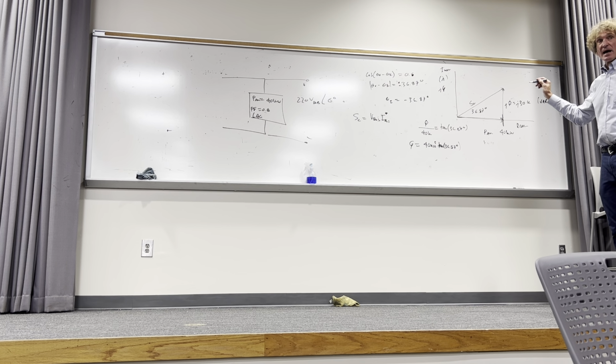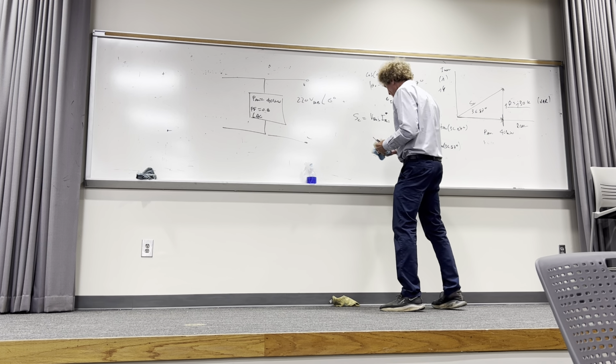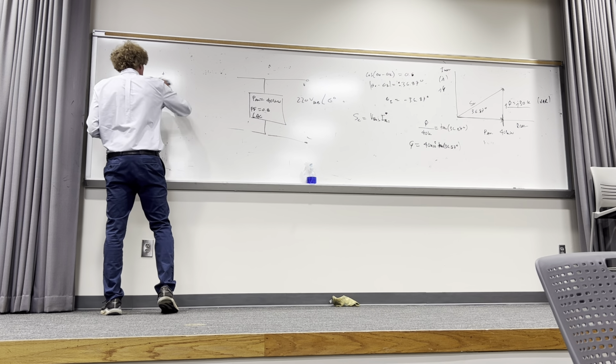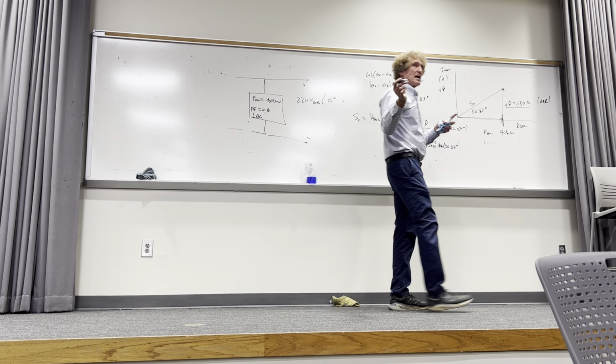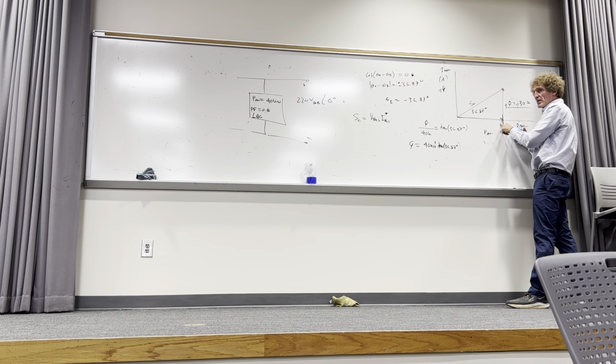With me? Right here. I'm going to redraw that over there. Please be attentive here. This is the stuff that stings people. So, what I've got over here, that's the old power triangle. And what I would do on your papers and stuff, this is the first thing you draw related to the actual load you're given. And by the way, they could give you S, they could give you the average power here, or the reactive power in the angle, but they have to give you enough information so you can create that power triangle. You all with me on this, class?